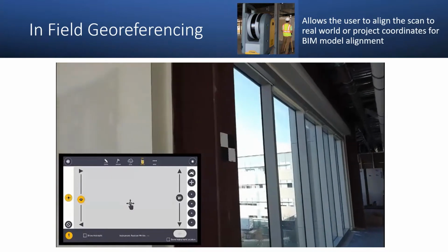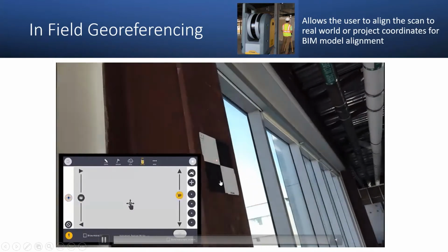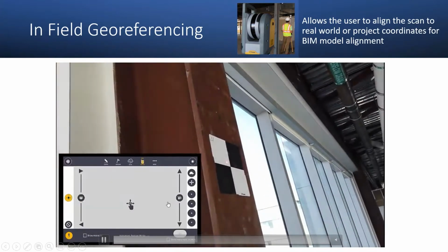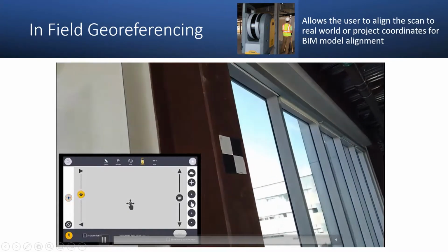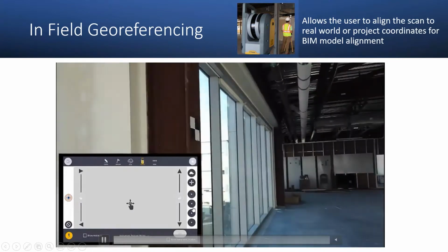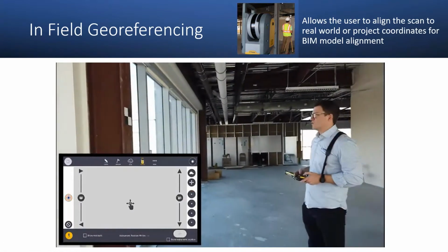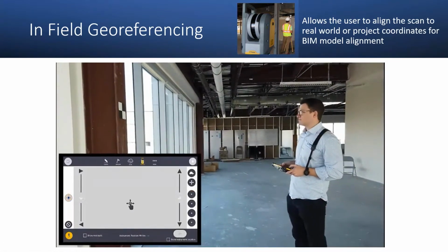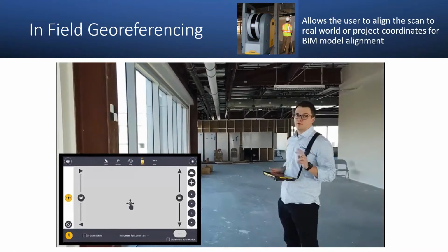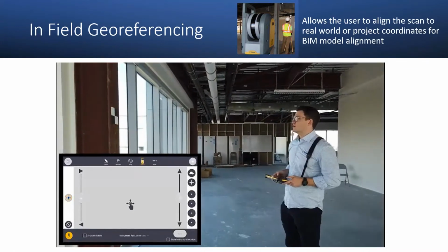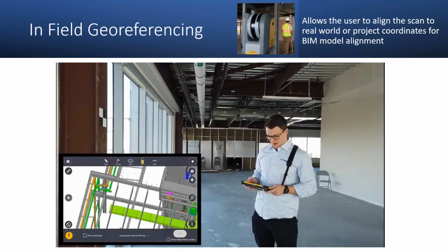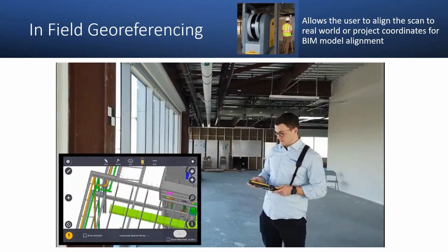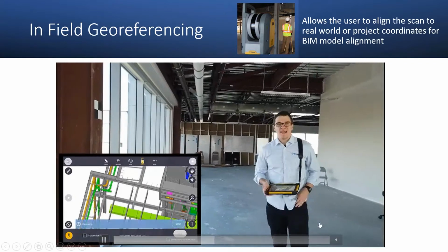Turn on the laser. You'll see the laser being there, and just using the slider buttons, dynamic joystick, or what we call the little nudge buttons here, being able to nudge that laser left or right to get it to where we want it. Hit the measure button. It usually takes about 8 seconds to measure. Once we do that, we're going to see it's set up.